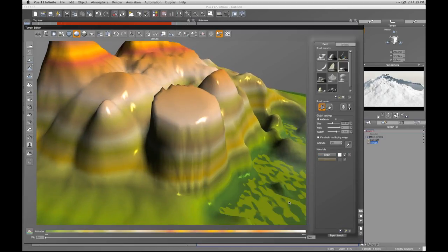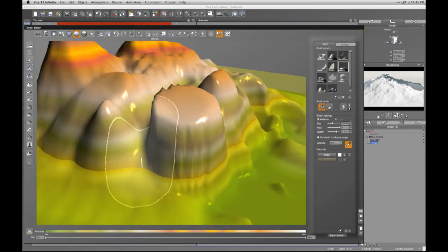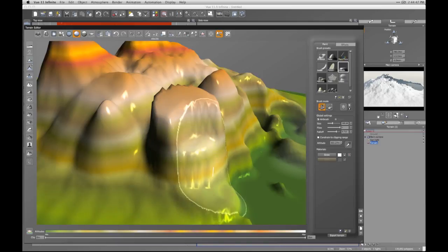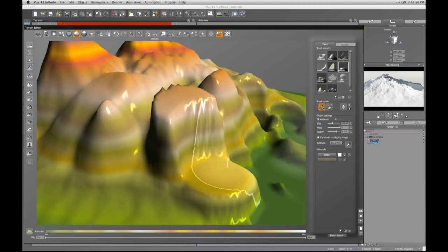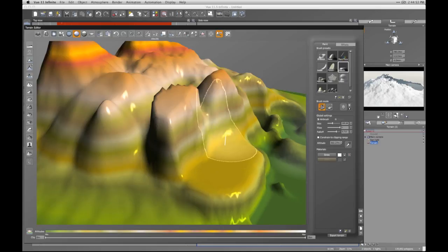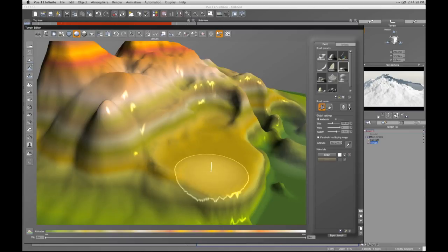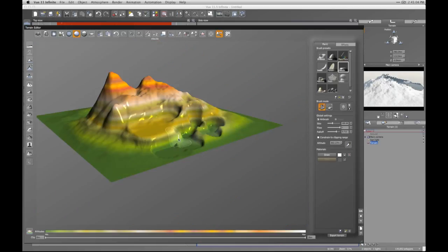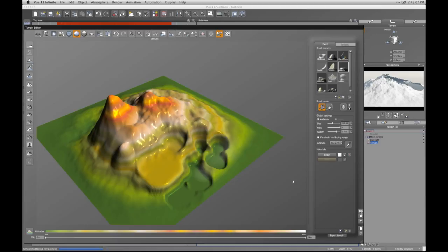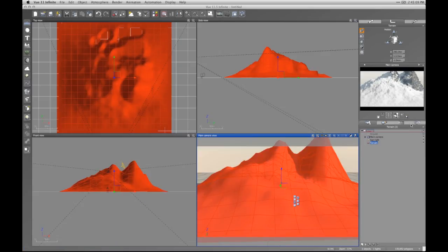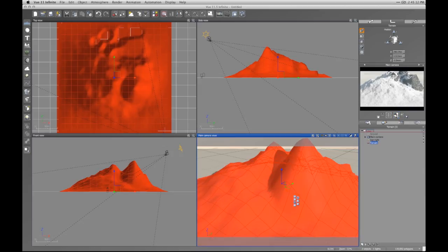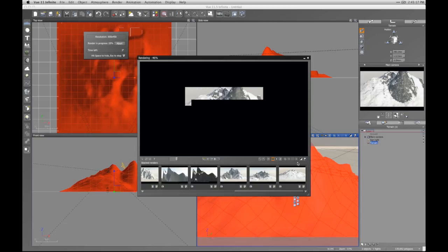The altitude is very handy. What you do is you can actually set the altitude manually, or you can use this little eyedropper. So let's say I'll click on that yellow line there. So now I can just go in and paint that altitude in. So really good for making plateaus and level areas. Alright, just gonna carve into this a little bit. And when we're done with that, we can hit OK, and we'll see in here our beautiful rocky, snowy terrain forming.